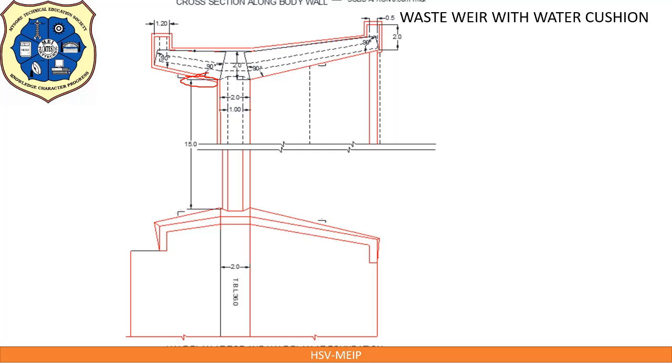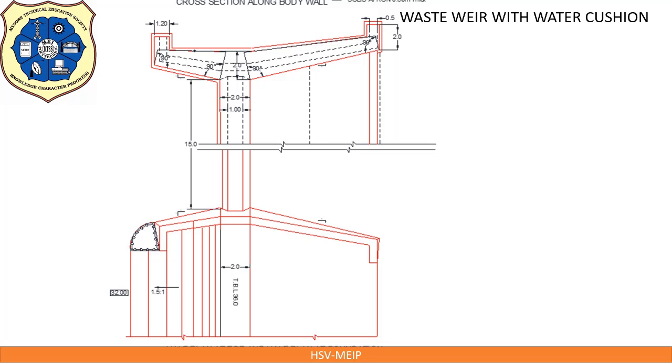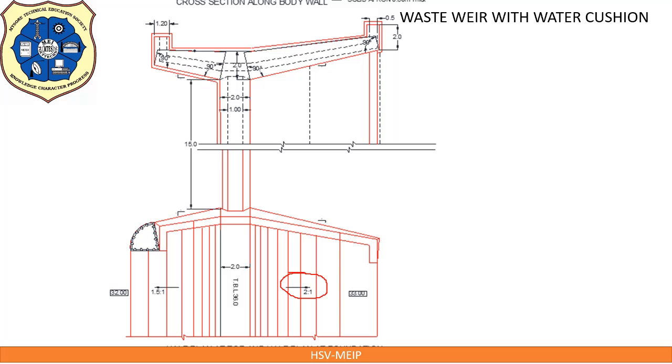From this point to this point is the length of the weir. Show rough stone revetment for balanced portion of earthen bund. Show sloping lines of earthen bund 1.5:1 on upstream side. Show sloping lines of earthen bund 2:1 on downstream side. Draw vertical lines at 4 meter and edge of cutoff wall indicating solid apron.